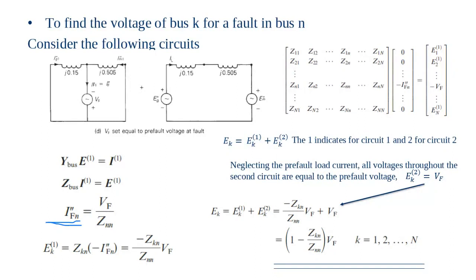Why? Maybe the fault disappeared. Maybe the tractor just touches and leaves and goes on. So there is a fault at the beginning, high current, and then it disappeared. The fault cleared away. Then the circuit breaker opens and recloses again.